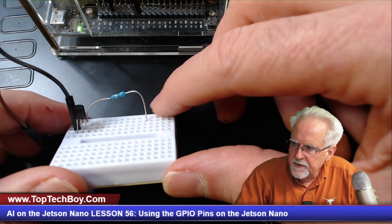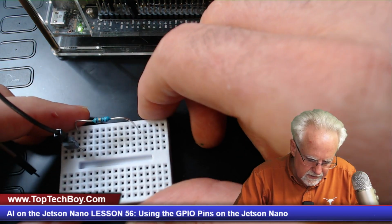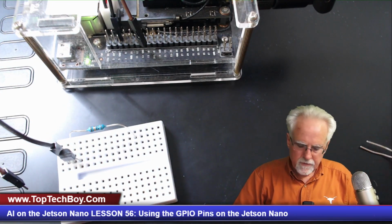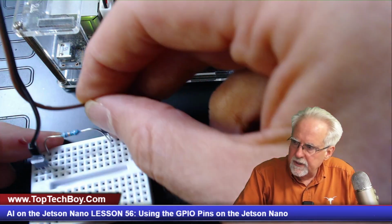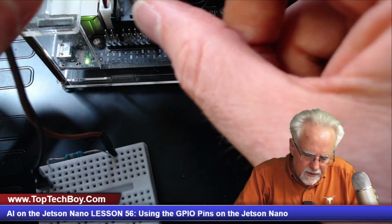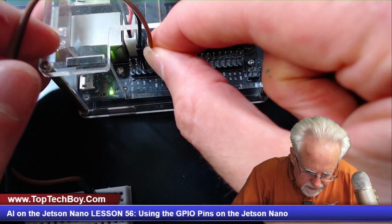And now this other end of that resistor needs to go to the control signal coming off the Jetson Nano. And for us, that is going to be pin 7. All right, so I'm going to connect to the other side of that resistor, and then I'm going to come over here and go to pin 7.